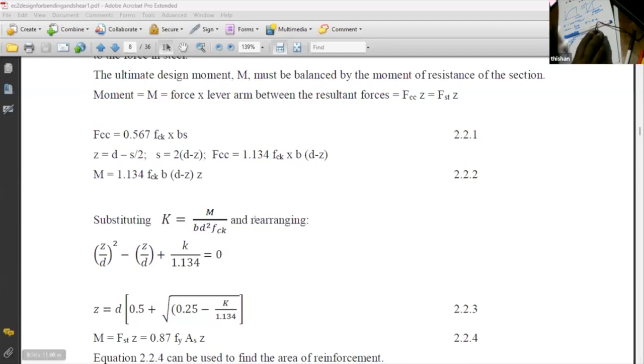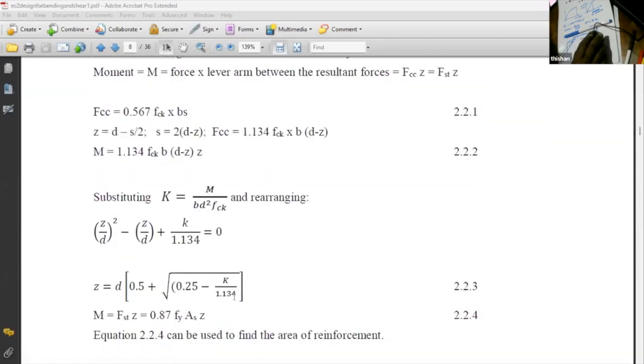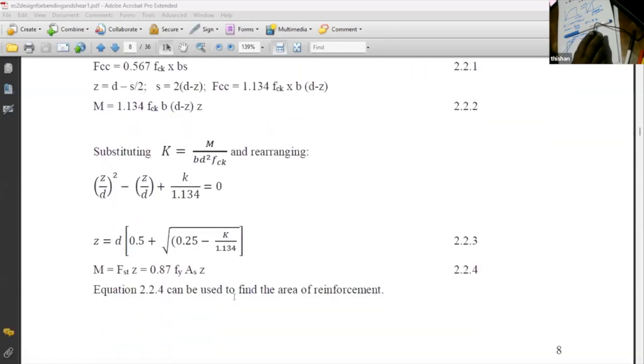The moment you know the K value, Z is known as a function of d, with maximum and minimum values 0.82d and 0.95d. Whatever Z you use should be in between those values. But if Z is more than 0.95d, we still consider it as equal to 0.95d.